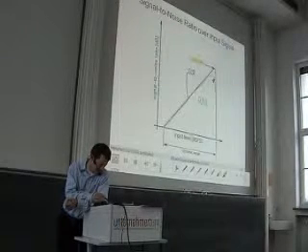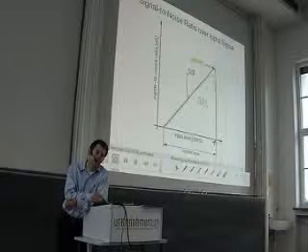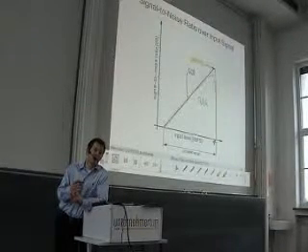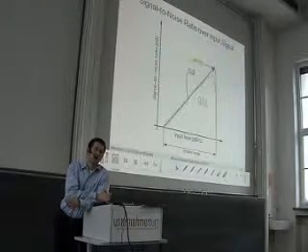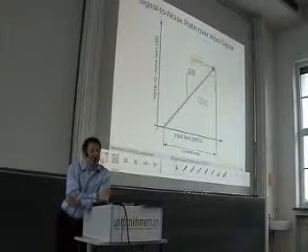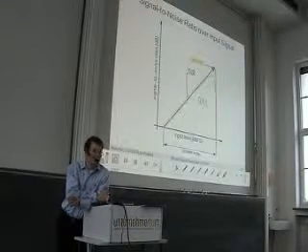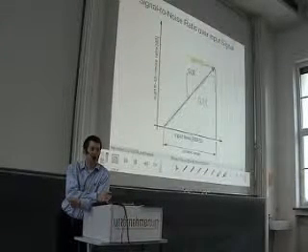If we have a collapse like this, you cannot use the device here, but you have to adjust your level plan to make sure that this overloading does not occur in your application. There are ADCs that do not have this effect, but for sure many of them do.